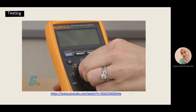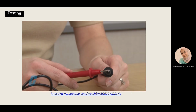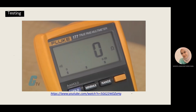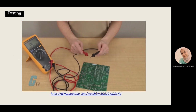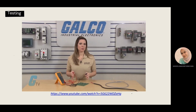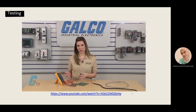I will turn on my multimeter to the desired test function and check to see if it is in working condition by touching the two leads together. Most multimeters will beep when touched together. The value on the multimeter will either show a 0 or a low value. This is because some multimeters will be checking for voltage or resistance when testing for continuity.